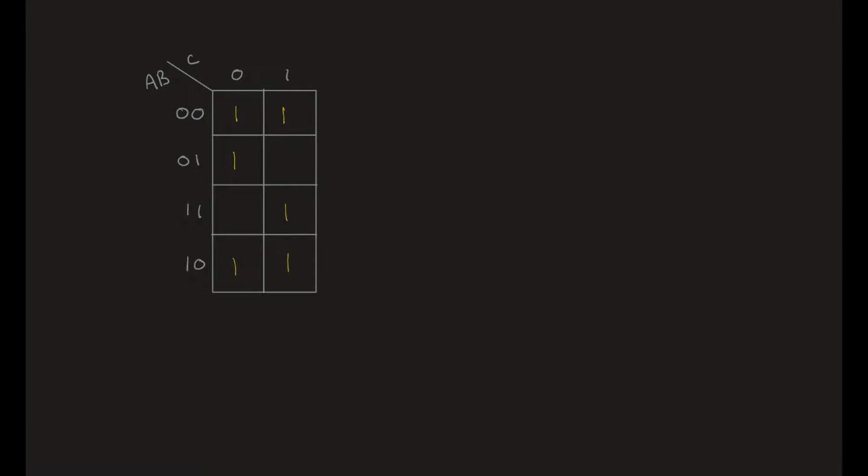What is the biggest group you think we can make? I'll give you a second. How many of you said a group of 2? It's true, we could do a group of 2, but I think we can go bigger. What about this? Notice if I group these 2 with these 2. You think I'm tricking you, right? Remember, I said you have to think of this as a sphere. This is next to this is next to this, and so on. And so wraparound is okay. Those 2 at the top are connected to the 2 at the bottom.